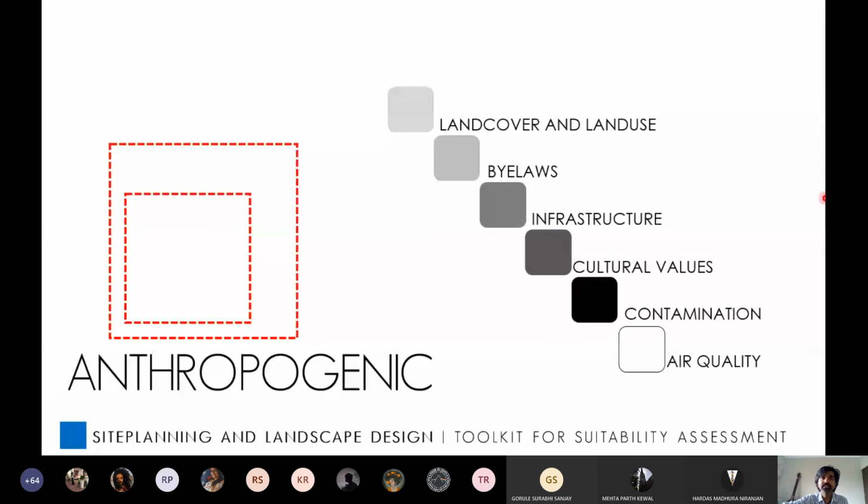So you need to know where the drain is. You need to know where the sewage line is, because otherwise you will design everything and at the end you will realize, oh God, my STP is in the southernmost edge, which is the lowest point of my site. But the sewage line which has been put in by the municipal authorities is like 5 meters above, on the other side, where my road access is. So it doesn't work that way, because in that case you'll have to pump up the extra.